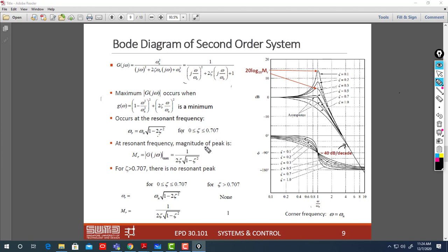Actually, if you get the chance later to work on some damping system, you will experience that it's not exactly the same. It's close to the natural frequency, but it's not. You can even zoom here and see exactly where the peak is. For example, at 0.1, if you have 0.05, maybe you can find it closely. Look at here at 0.5: the peak is not exactly at omega n. It changes to be close to omega n, depending on zeta.